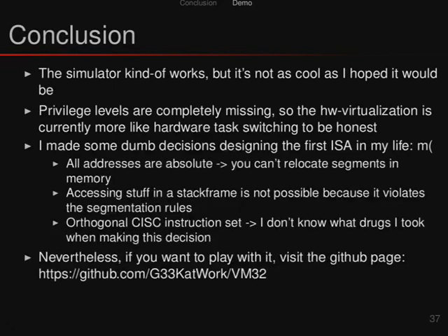So that was something I discovered when implementing real code running on the CPU, and I fixed that by introducing the get argument construct. But you could just say, okay, accessing the stack segment with register 30, so the stack pointer, and register 29 for the base pointer is allowed on data and code segments, for example.